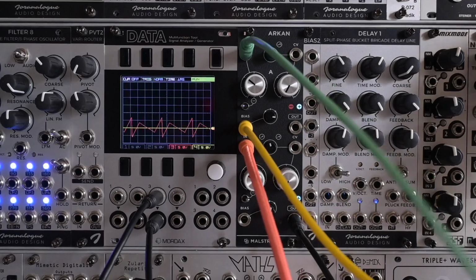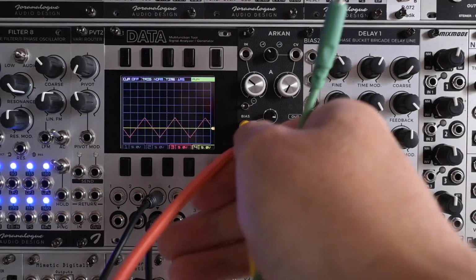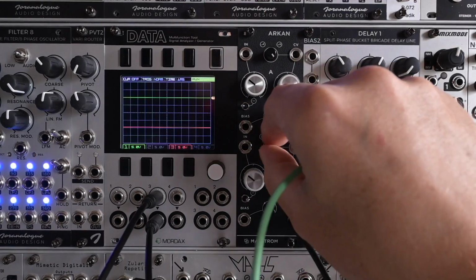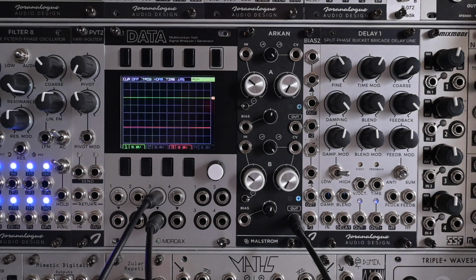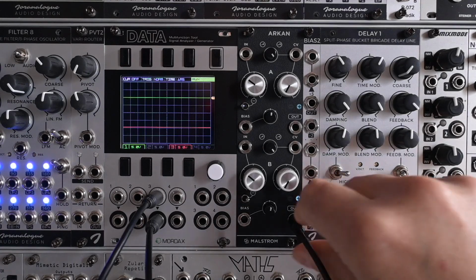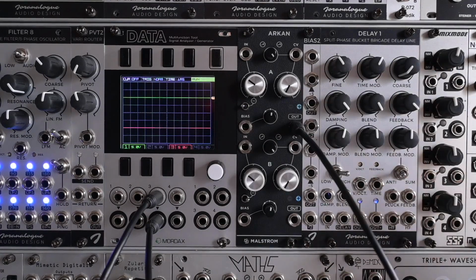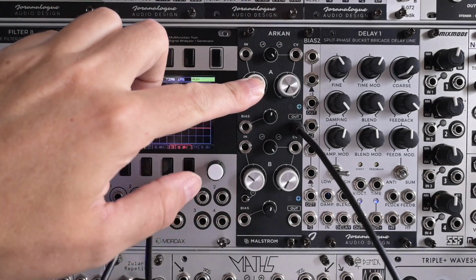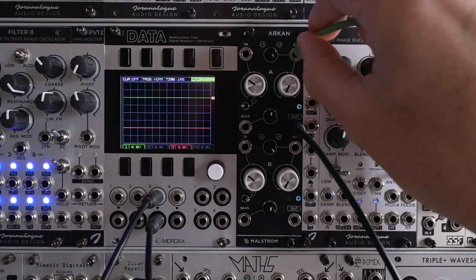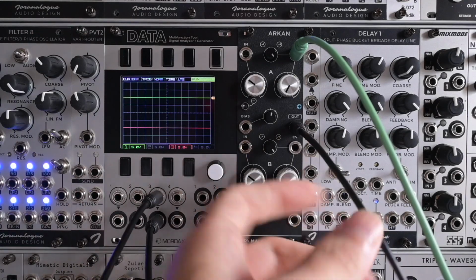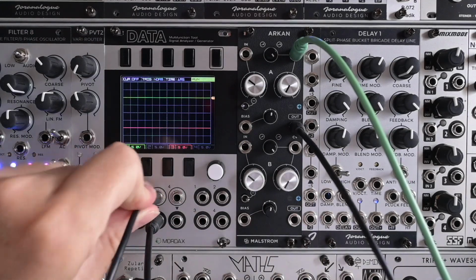I know I said one more thing, but I just thought of another thing that I really want to show you. You can use these curvature controls to change the shape of a wave. It's not something that you would expect to be able to do with a VCA. So I already showed you that this CV input controls the amplitude or inversion of whatever we are sending in here. So when we send a signal into the CV input, and nothing into the signal input, you would indeed expect that you don't get any signal from the output here.